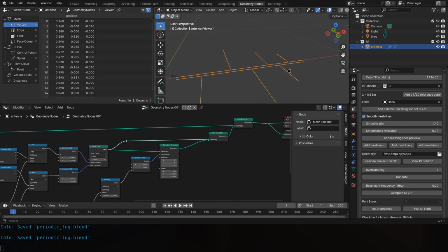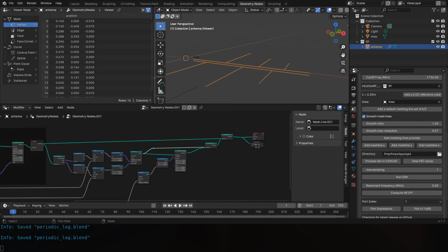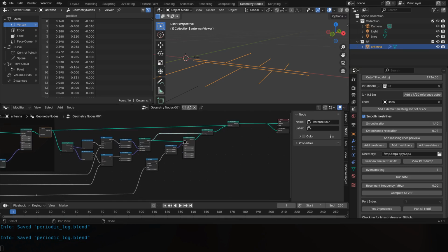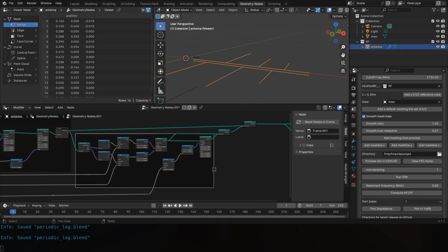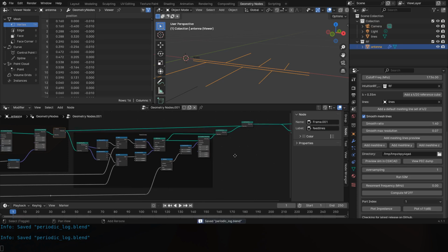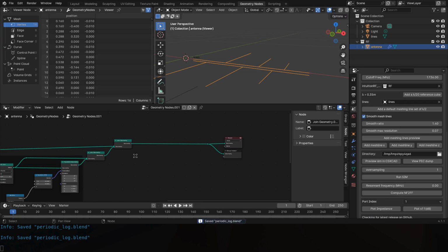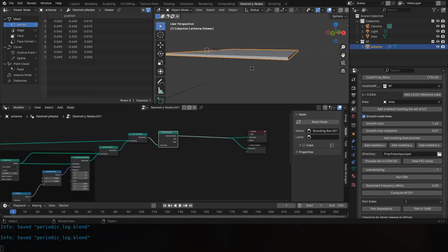Okay, now we need to add the port at the front, and we need to add a short at the back, connect those two lines at the back. Okay, so we can use that bounding box trick again. Take this output, so let's call those the feed lines. And I'm going to use the bounding box again, like this. So that's your bounding box.